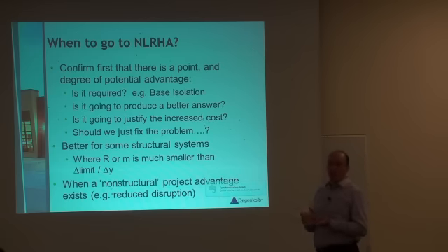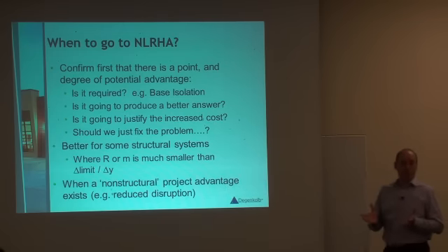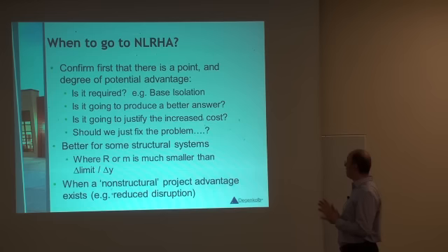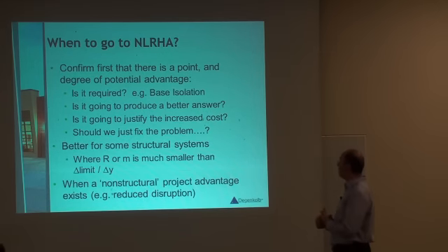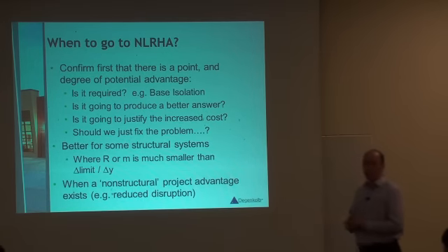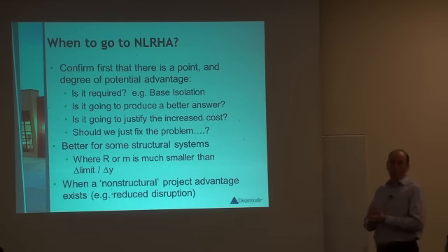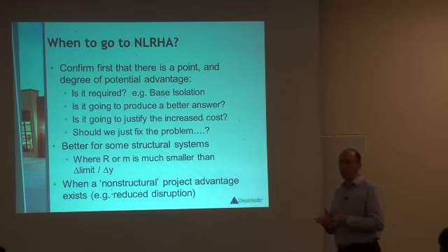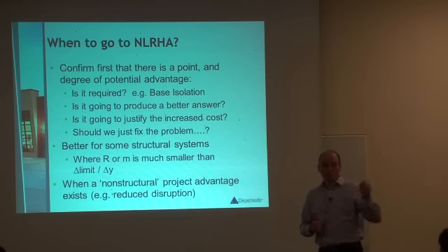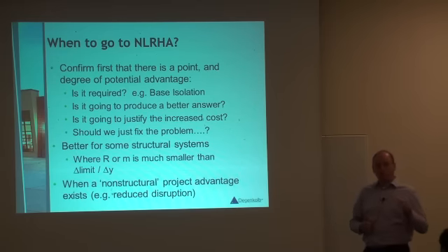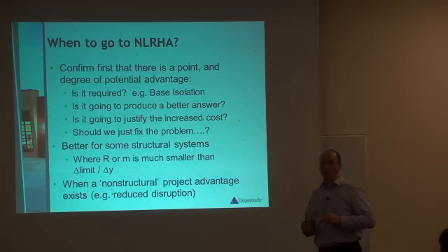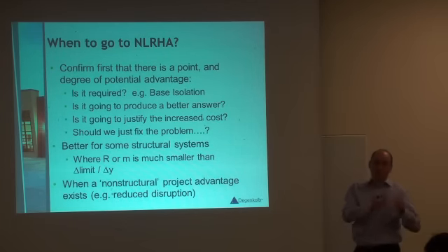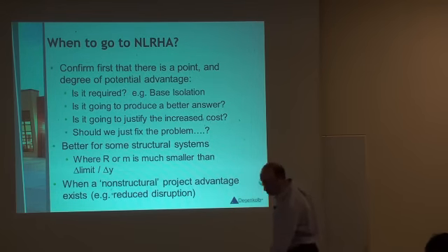We don't usually know if it's going to give us a better answer. Sometimes it gives us an answer that we don't like. So we just have to be careful. It's going to be definitely more expensive. And sometimes we can avoid doing it by fixing the problem we're trying to solve to start with. So very often we use response history analysis in practice because we are not meeting one requirement of the code, and doing nonlinear analysis is one way to go around that. Well, sometimes it's easier to fix the problem than to do the analysis. It's not going to make the analyst happy, but that's the reality of things.